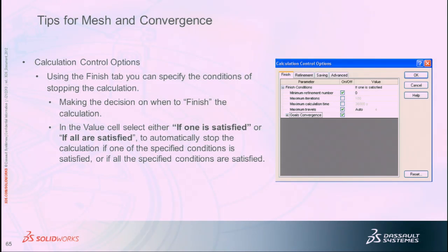There are some CFD programs that don't have an automatic stop. You as a user decide when to stop it, because the developers are too scared to do that in some other models. But in Flow Simulation, there is an automatic stopping. It's usually very good. There are times where it doesn't need to run as long and you can stop it early, or there are times where you may have to extend it. That doesn't happen very often, the extending part of it, but in some cases it does.